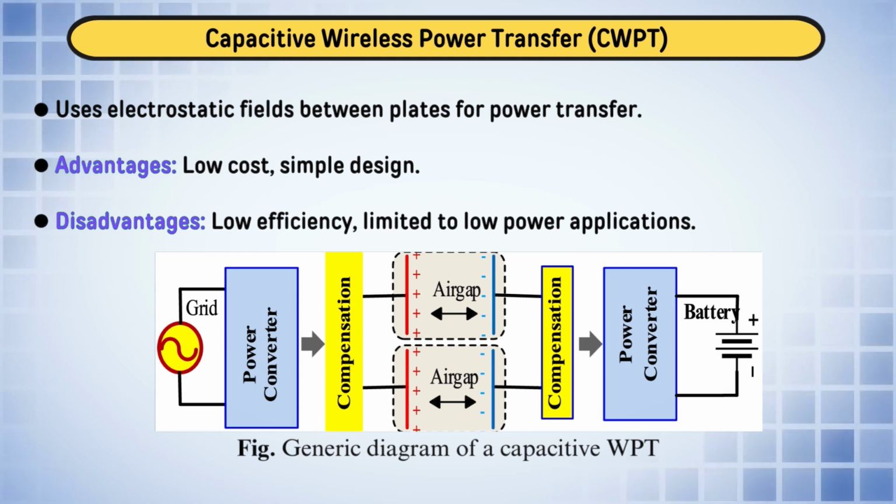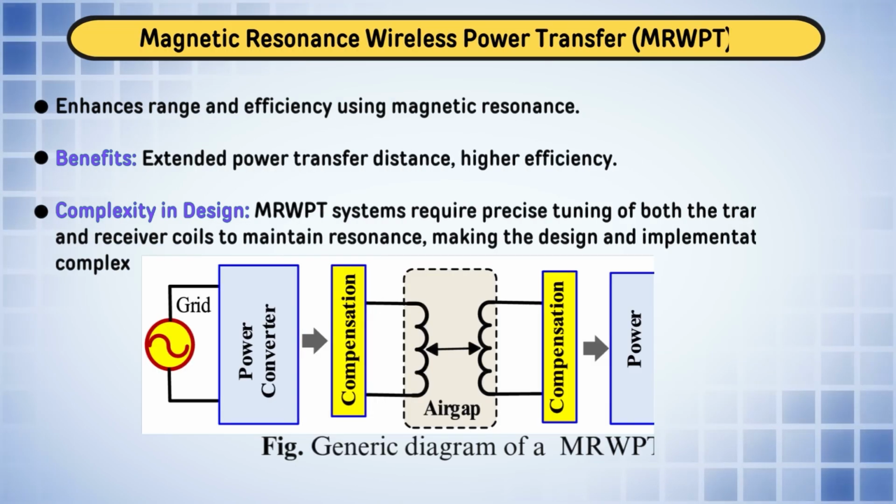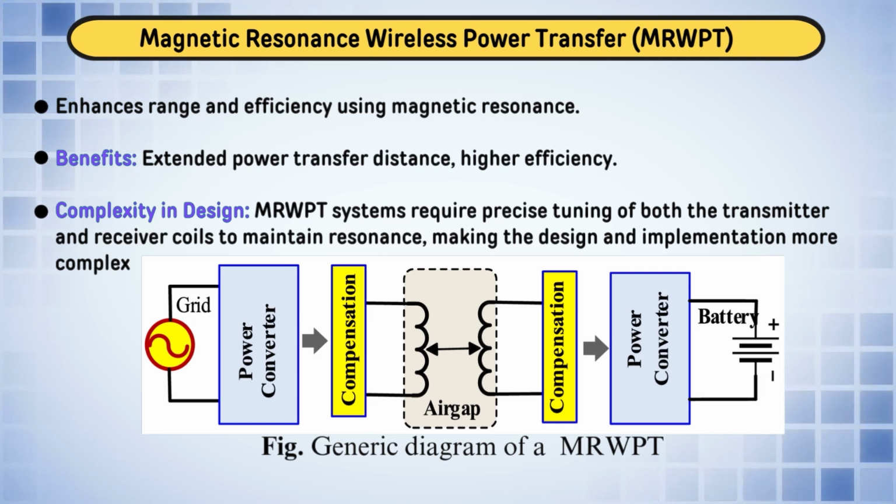Now, the operation of the buck converter: suppose we have provided an on signal to this switch. As soon as the switch is on, the inductor stores the energy, and the moment you switch off the switch, the stored energy of the inductor freewheels through this diode. So, the capacitor gets charged and the capacitor will supply this energy to the load or to the battery.